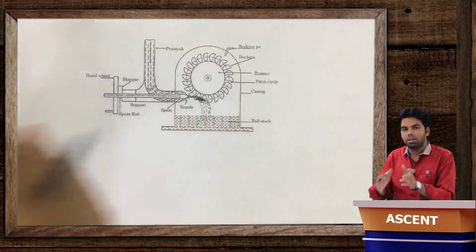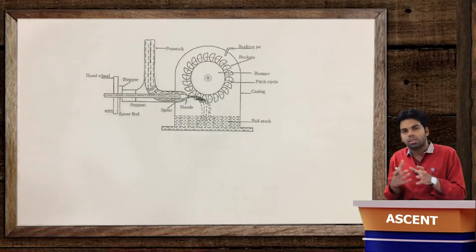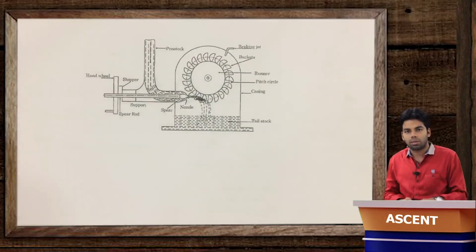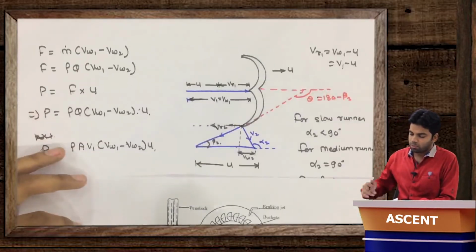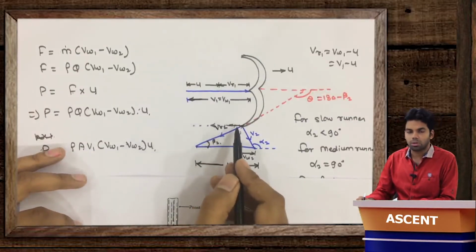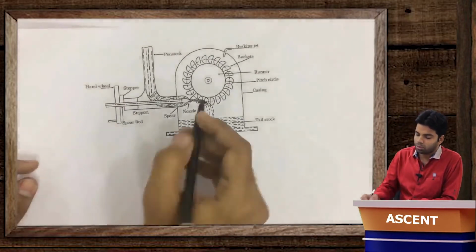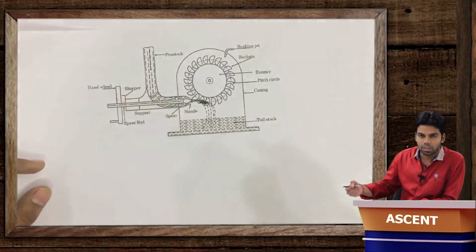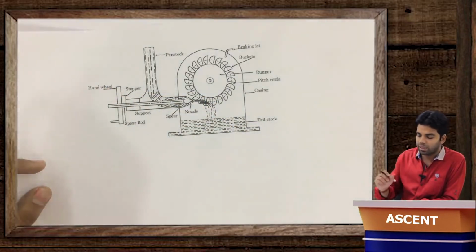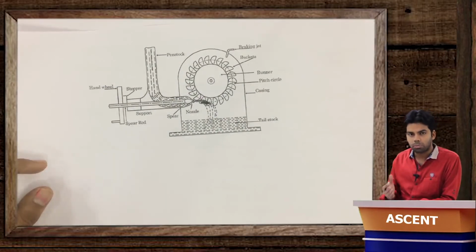it will hit the coming blade, and it will hit the other blade, and what will happen? It will retard the motion of that blade. Getting this or not? Okay, so this actually is not possible. Having beta 2 equal to 0 is not viable. Why? Because if beta 2 is equal to 0, the jet will hit the coming blade, and finally it will retard that motion. So the value of beta 2 should not be equal to 0.